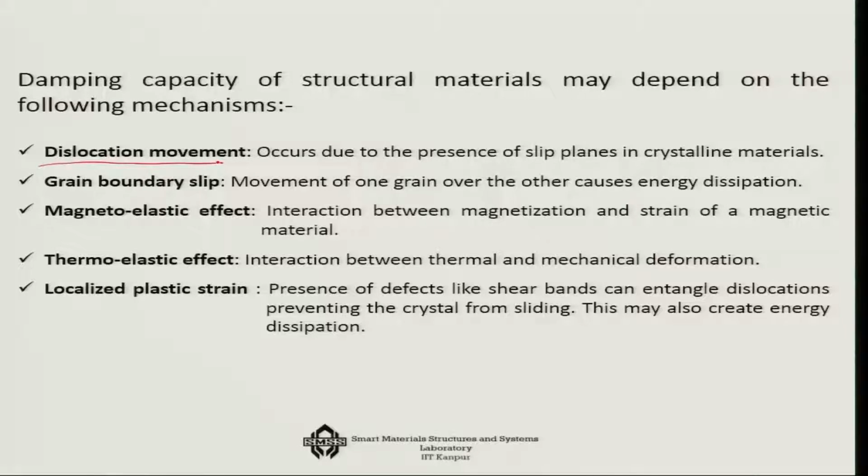Now, during vibration, energy can be supplied such that this slip plane movement occurs and it goes towards the grain boundary, and hence this process will consume some amount of energy in terms of dislocation movement, and effectively that will be reflected as an increase in damping of the system. So, dislocation movement contributes to damping. Similarly, there can be grain boundary slip.